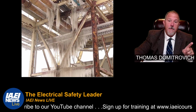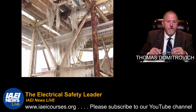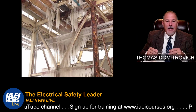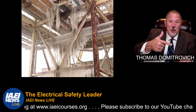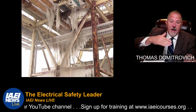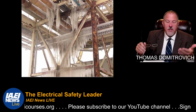So environmental conditions considerations are very important. If you know you're going to have ice weight, then you might have to plan for it, right? So ice loads. Typically, I mean, this is a pretty harsh installation. What you would typically see is like a glaze on top of your cable tray, okay? And it's hard to stop that, outside of putting your cable tray indoor, which would probably defeat the purpose of why you're using it and where you're using it. But what you can do is include that in your weight calculation. So there are ice loads, there's methods to do that, snow load as well.